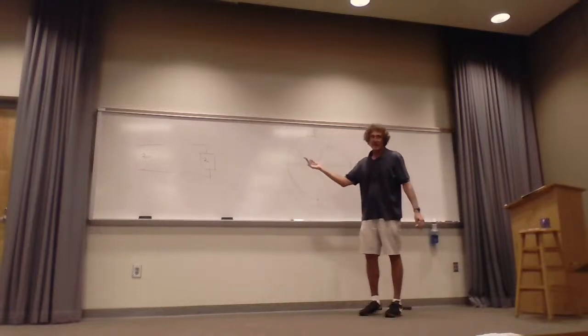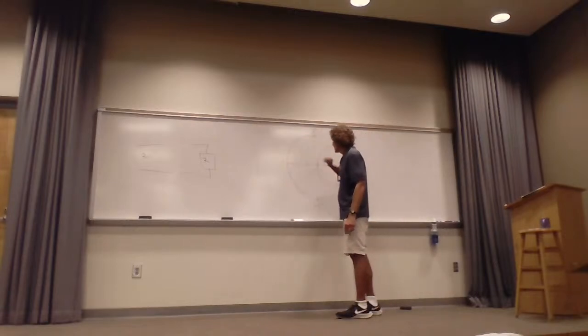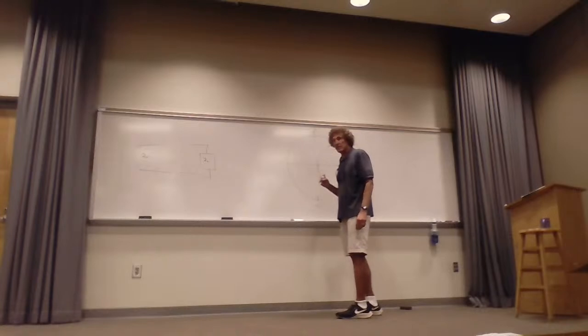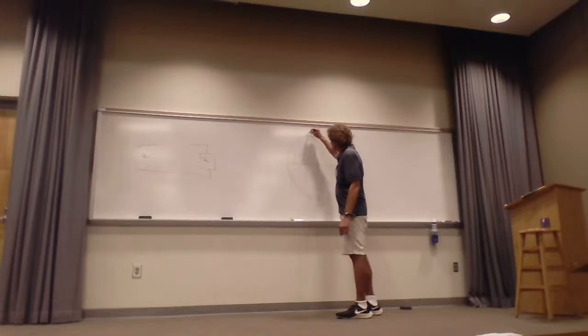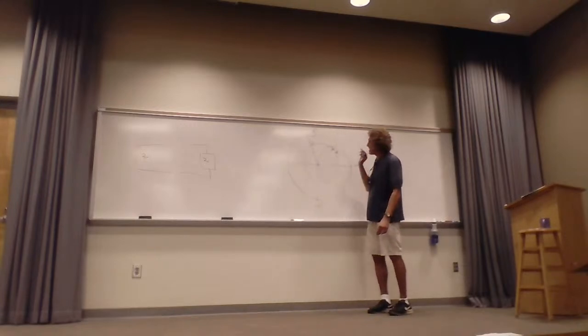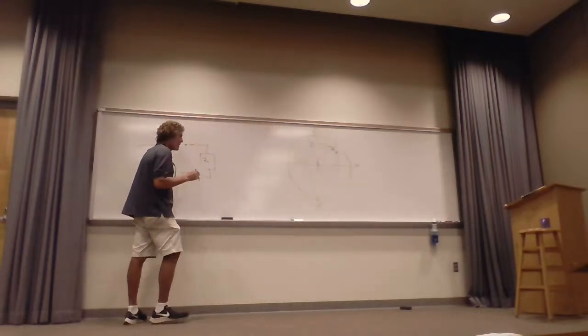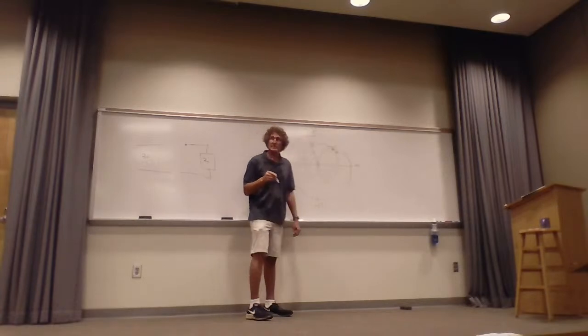And we know if we have ZL, and we come in the Smith chart at any point, say here, then there's a couple ways we can deal with it. If we've got a series connection, right? I'm just going to talk my way through it. This is bringing it back. I would take this and I would draw the same radius all the way around here, and I would move from here, my point 1, to point 2, right? And then I'd figure out how far I moved. Y'all with me? Now I move down to here, and then I'd figure out what impedances I'd add.